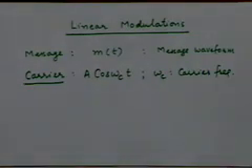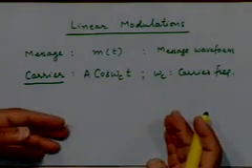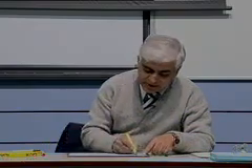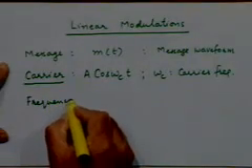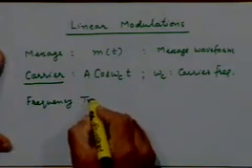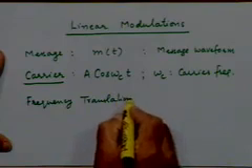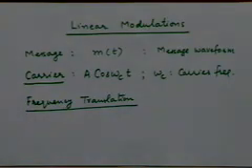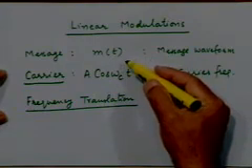Now as we have learnt from our review of signals and systems, there is a very basic technique for frequency translation, and that's one of the main objectives of modulation, right? We want to carry out a frequency translation of the message, which is a baseband or low pass signal, to around some other frequency omega c, to convert it into a band pass signal, right? And the basic frequency translation theorem that we have learned about, which is also known by the name of modulation theorem, and now you can appreciate the reason for that name, is what is the basic frequency translation technique that we know of? Just multiply these two signals in the time domain.